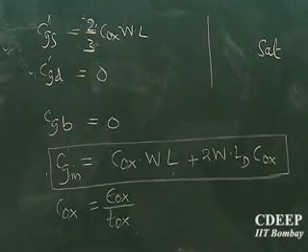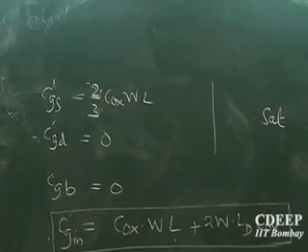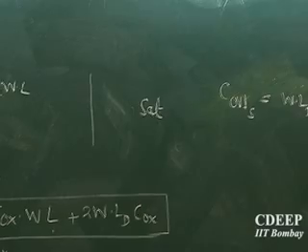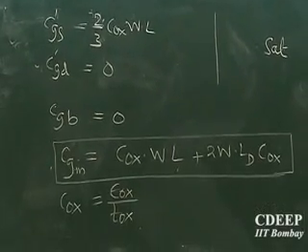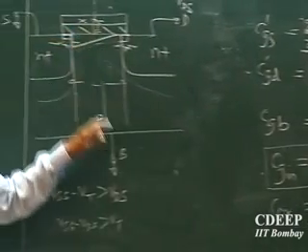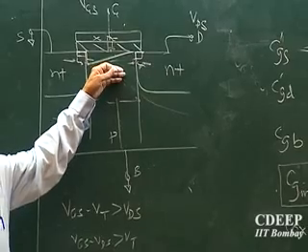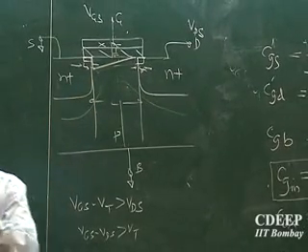Once the N channel is created, the bulk is screened, because the capacitance there is only depletion, which is much larger. So, as if we are saying, this gate has no more control on this area, it's a neutral area now. Whereas I have not yet finished all of my capacitances.